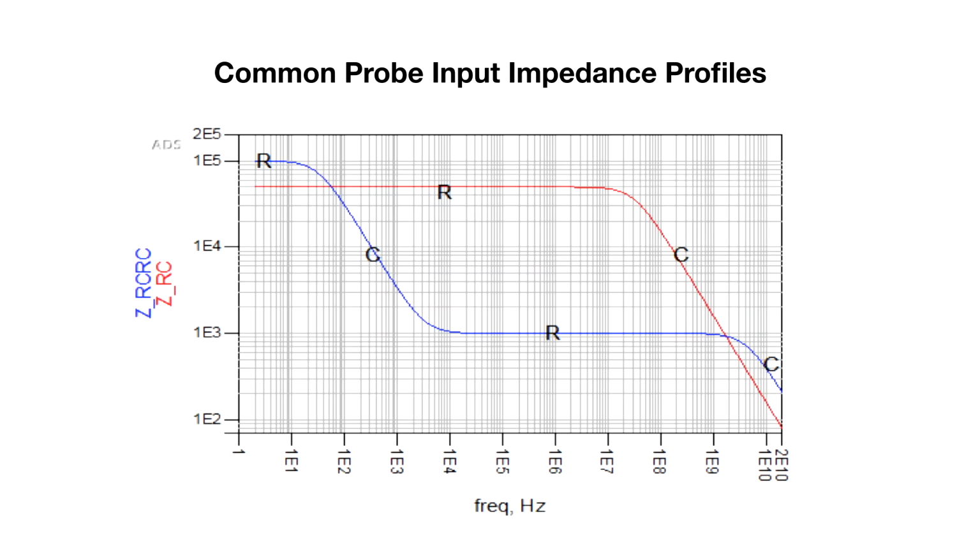At high frequencies, equivalent to high-speed digital signals today, the resistance and capacitance vary across the frequencies. This standard way of looking at probe impedance is an input impedance profile plot. The plot relates the probe impedance versus frequency. Let's take a look at two common profiles.